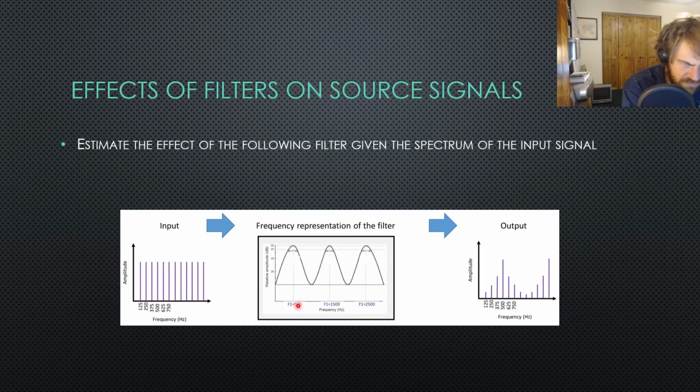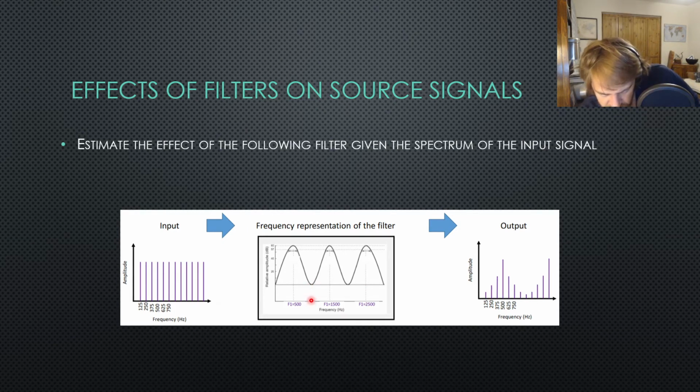You can also, if you look at the center frequency here, which is 500, the center frequency here is 1500. And so halfway between those is going to be 1000. And that's where the sound is going to pass the least. Notice that it doesn't hit the 0 mark. The 0 mark is down here. So we will expect that none of our sound will be attenuated completely. And that's actually what we see here. None of our sound is attenuated completely. And this should be 1000.